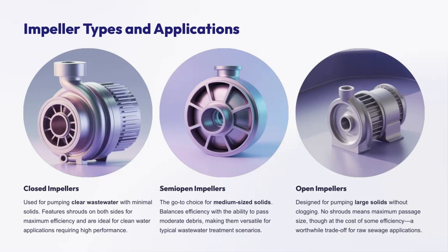Let's take a closer look at the different types of impellers and their applications. First up, we have closed impellers. These are used mainly for pumping clear wastewater with minimal solids. They feature shrouds on both sides, which helps maximize efficiency.